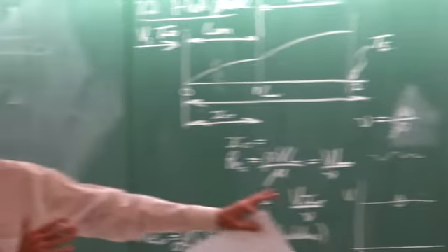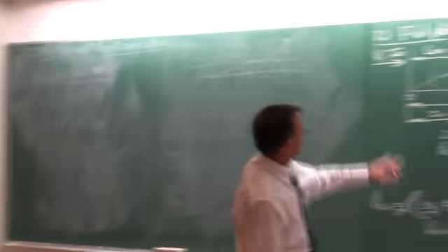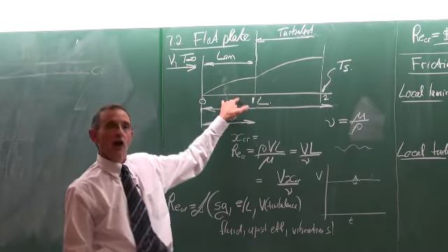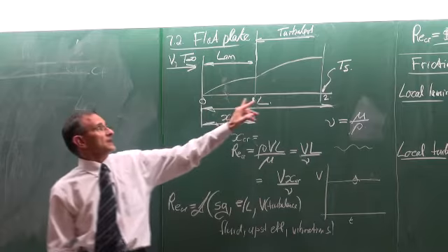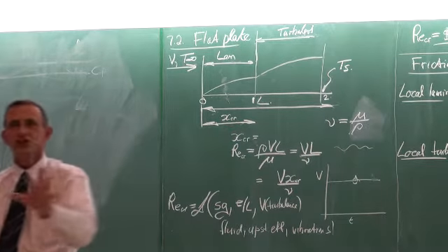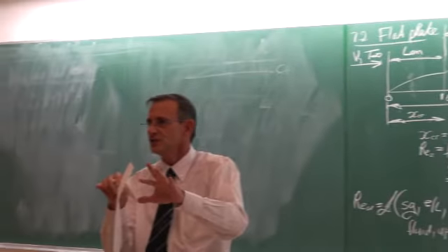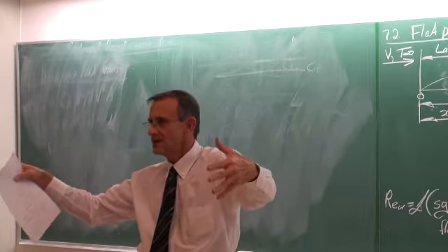Okay, that's now the fluid mechanics part. Now we have to do the same for the heat transfer part. Okay, for the heat transfer part again, there's going to be a local Nusselt number if the flow is laminar. There's going to be a local one for turbulent, and for each one of them we want the average values, and we would like the average for the two together.